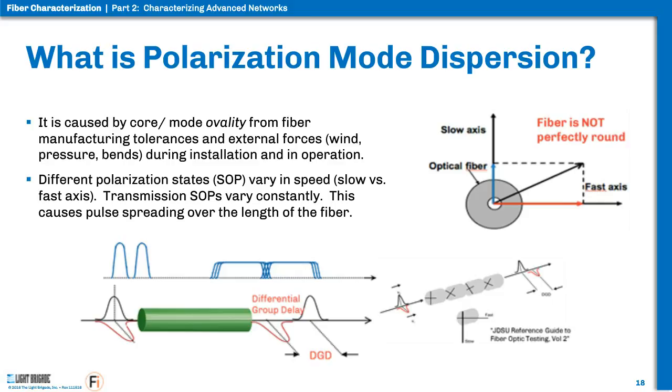If you think about one polarization state vertically and the other horizontally, as these travel down the fiber, they spread out, the slower versus the faster ones, and they end up at the other end spread out due to the signal in those different polarization states. These are constantly changing, so the signal that's in one state will switch to the other state and back again.